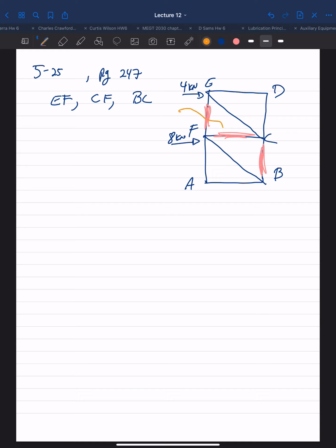So our cut will go like here. Okay? So that cut separates the bottom half from the top half. So if we work the top half, we do not have to worry about any support reactions. So let's redraw our free body diagram after our section has been made.